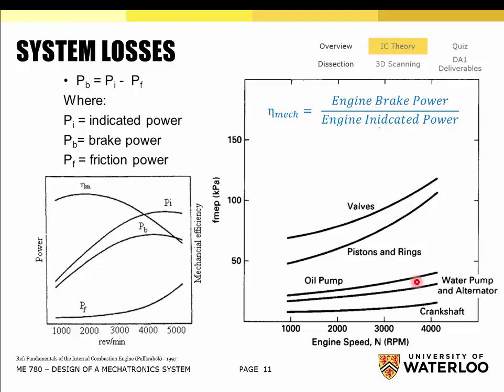So those rings are directly sliding against the cylinder wall as it reciprocates. There's a lot of energy lost to that. So optimizing the frictional coefficients and the way that everything works in terms of the spring tension of the rings and how much pressure is distributed on the cylinder walls, that's something that automakers focus on for years of their development cycles.